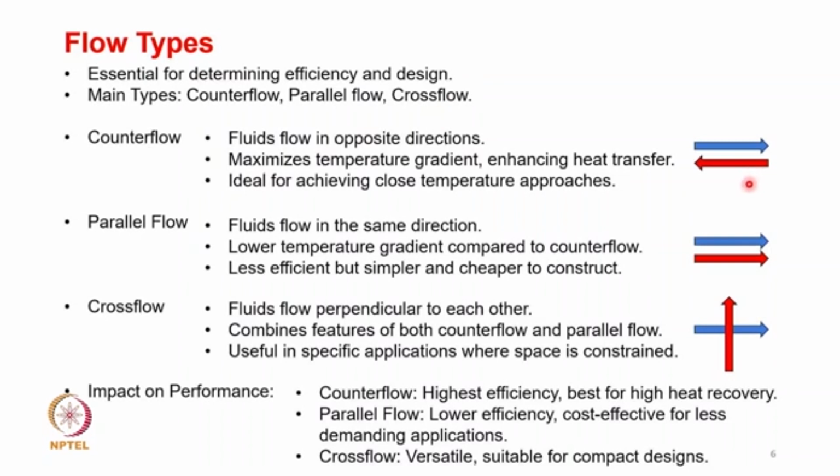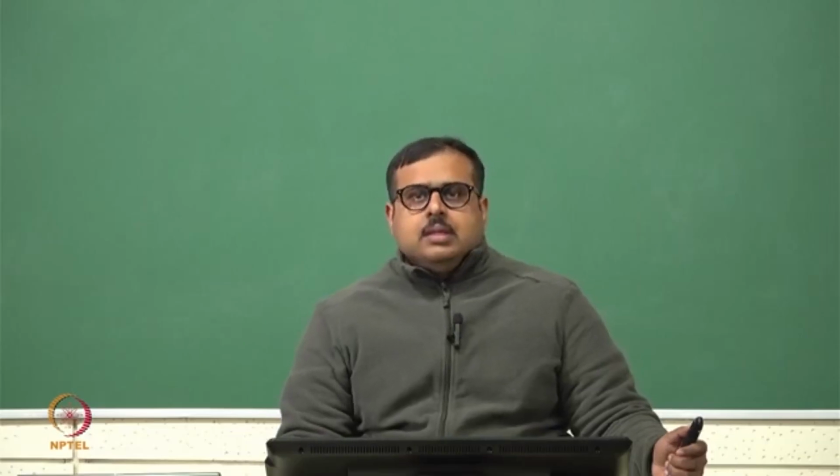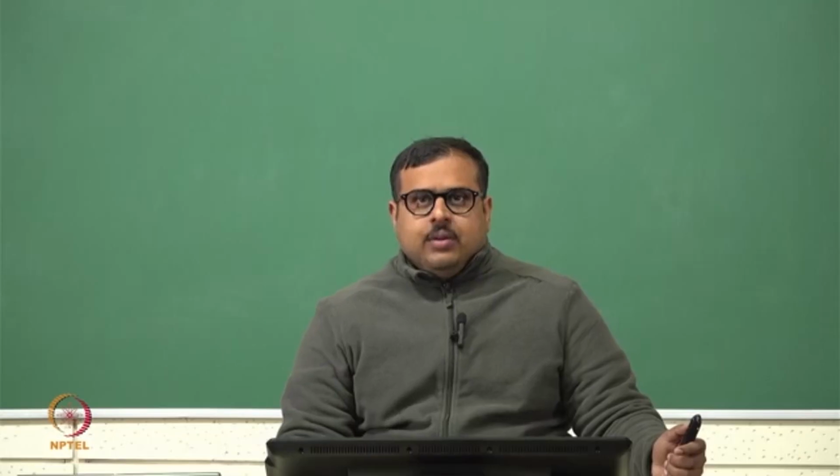The first one that you see over here is the counter flow, which essentially means that the cold fluid and the hot fluid are passing against each other. So the direction of the cold fluid is opposite to the direction of the flow of the hot fluid. The advantage of such a flow is that it increases the temperature gradient and thereby increases the heat transfer. So if you want to achieve close temperature approaches, counter flow is the most suitable flow pattern.